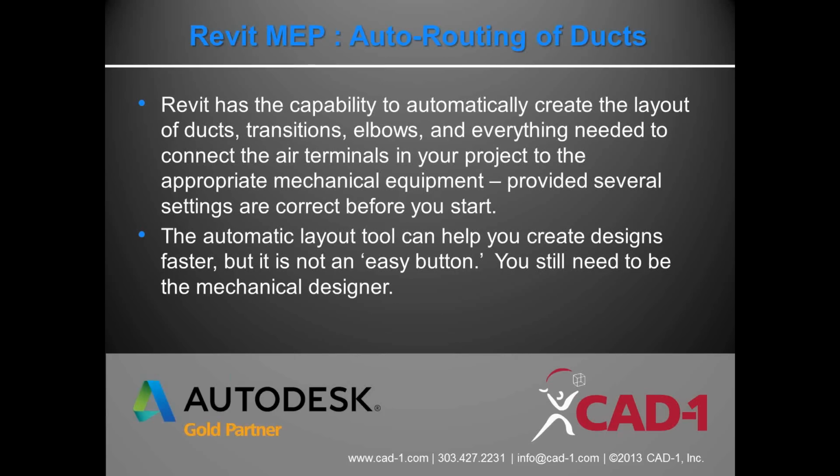So anyway, the bottom line is Revit can generate these duct layouts for you, but keep in mind that Revit, it's a computer. It doesn't know what you know. You still have to be the designer. You still have to be the engineer. You still have to know that there's going to be an exhaust hood in this area, so you have to move around that. You know that the beams are in certain places. They're going to change, and the designs are going to change.